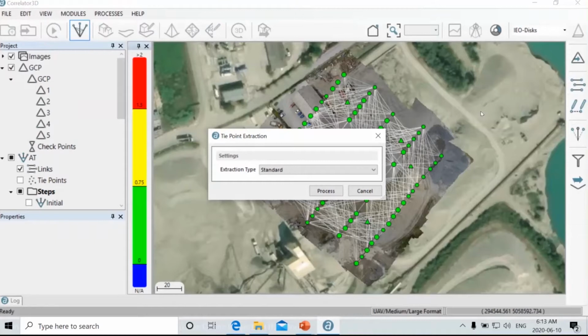So again, for a typical UAV project at SimActive, we recommend having a side overlap of maybe 50% minimum, and a front overlap of 70%. You can also raise this to 60% side lap and 80% front lap, but maybe not going higher than that, because it will just create more data than you need. So the overlap is a key part for the 3D reconstruction.